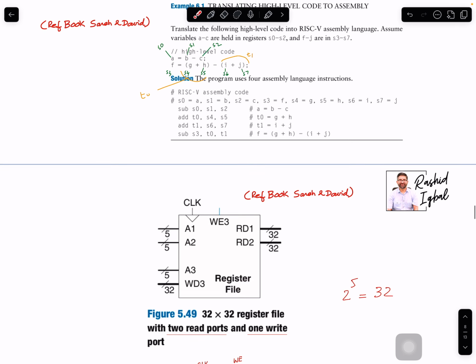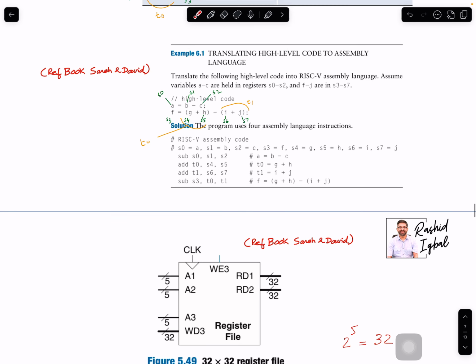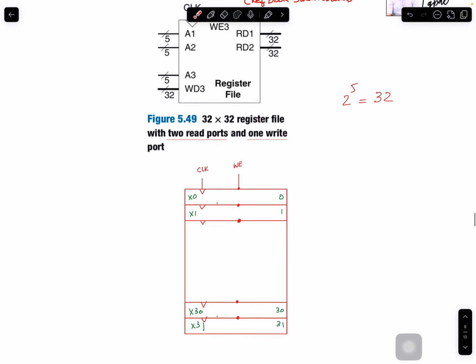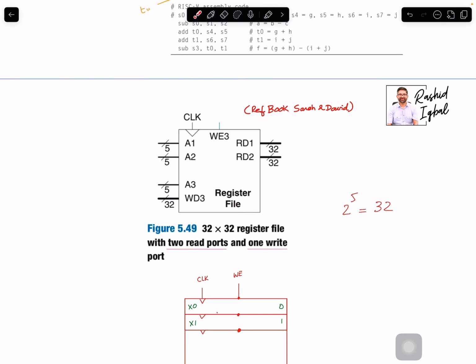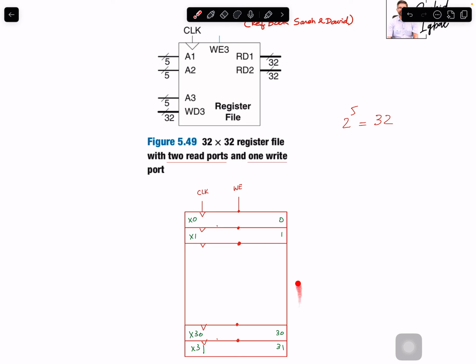So as you have seen, with add and subtract, every time on the right side you have two registers where the operation is happening and the output is written in another register. From that, the first thing we can see is that we need to put all the registers nicely structured together. We cannot let them just spread around the chip. Since we always access them, it is much more efficient for the timing and the design that you put them together with each other.